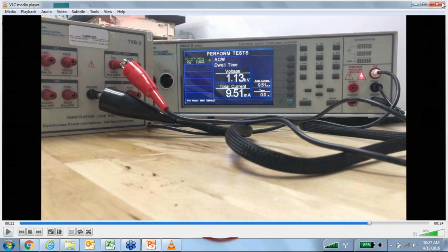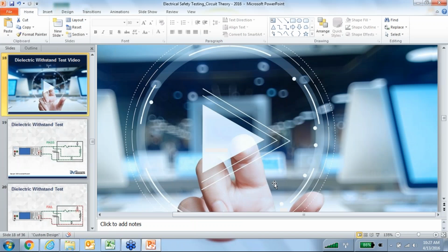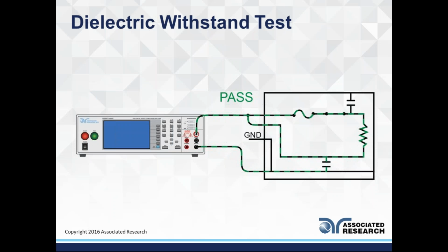let's go back to our circuits so we can kind of explain more of what's happening. So here's our pass. You can kind of disregard the moving green dashes because really when your Hipot passes, there's nothing moving. I do have an electric field there, but ideally in a pass, no current is flowing through this capacitor here.